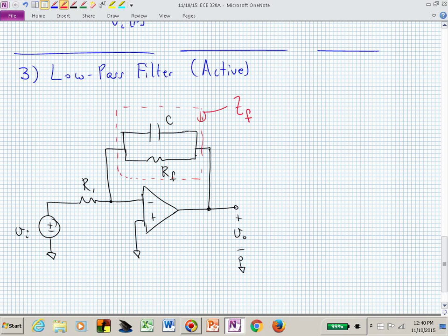If you need an inductor, a lot of times what you do is you actually cook one up by R's, C's, and active elements on your circuit board. You don't want to put this big piece of wire that's wrapped around the core in your circuit. So you can effectively do the same things with R's and C's, and that makes it cleaner.